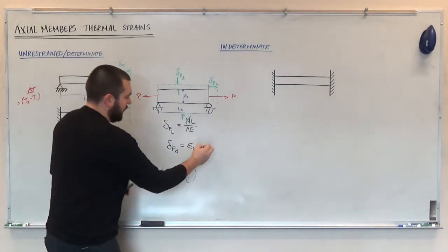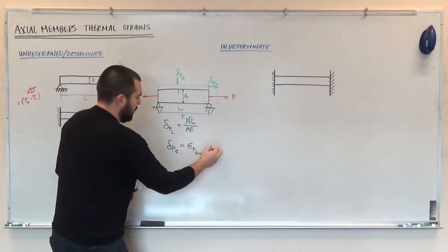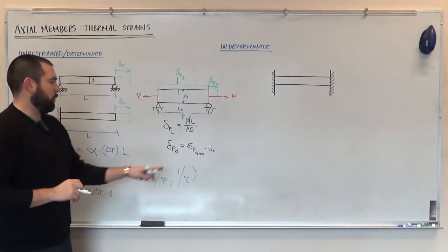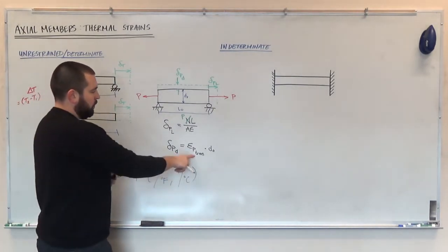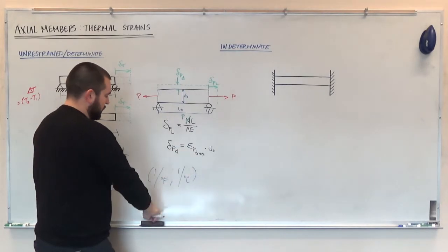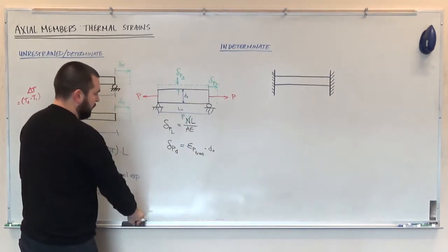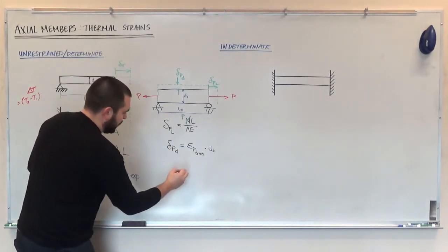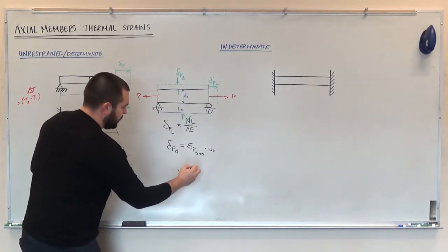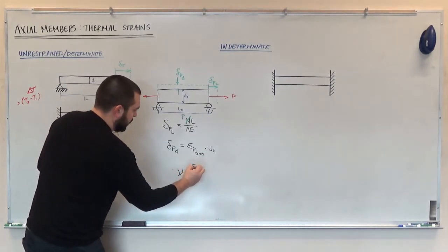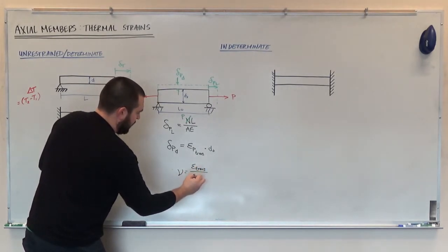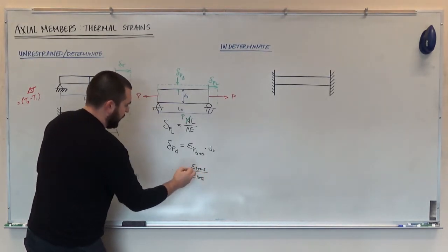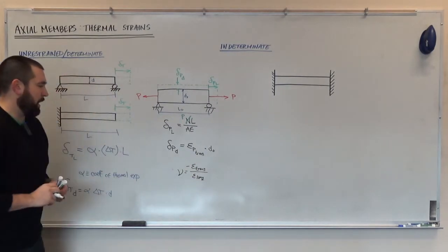And then we need to multiply it by the original width. This is where it gets a little bit tricky. This is where Poisson's Ratio comes into play. Here, to calculate the transverse strain, we need to use Poisson's Ratio. That said, Poisson's Ratio is equal to the transverse strain divided by the longitudinal strain, and there's a negative symbol out in front of this.